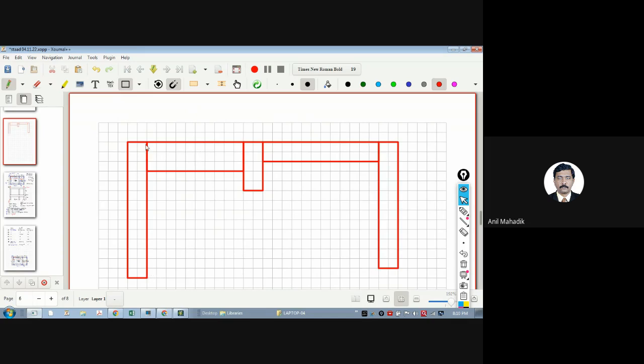This beam is resting on this column, and this is resting on this column and beam. Now you see that this beam has lesser depth than this. Now you are asking whether it should be the same size. By looking at this picture, what do you think will happen to this beam? Torsion, I guess. Torsion will come because there will be an unbalanced moment, due to this size difference, due to this eccentricity. There is an eccentricity here, you can see. Due to that there will be unbalanced moment.